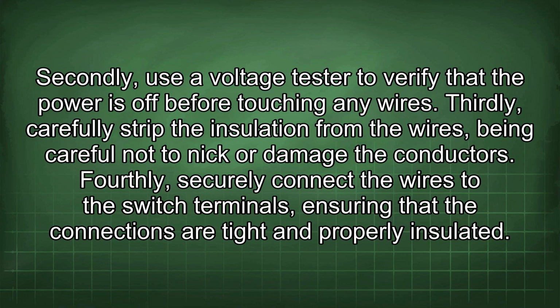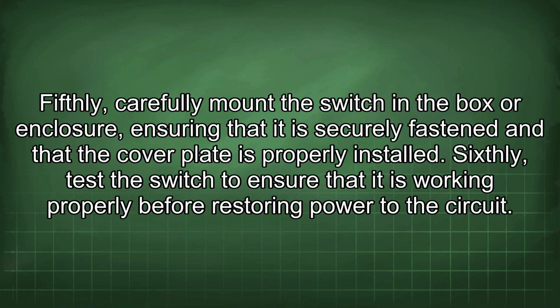Fourthly, securely connect the wires to the switch terminals, ensuring that the connections are tight and properly insulated. Fifthly, carefully mount the switch in the box or enclosure, ensuring that it is securely fastened and that the cover plate is properly installed. Sixthly, test the switch to ensure that it is working properly before restoring power to the circuit.